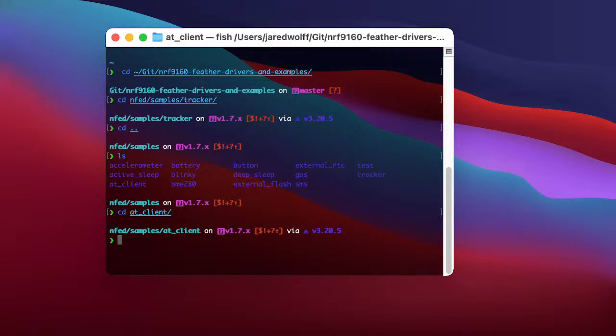Now what I recommend, at least for any type of Zephyr install, is that you set up a Python virtual environment for each project. This mostly keeps things contained between your different projects. So say you have different versions of Zephyr on your machine, or different projects that use different versions of Python, it can get pretty dang hairy.